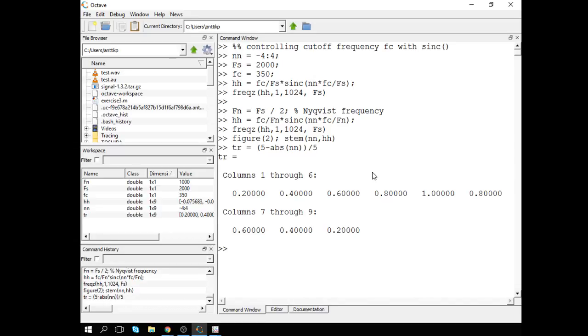Yeah, that's the triangular shape window. Now we can actually do the sinc again. Let's see, but we already have the sinc. Now we use the other window, not this box window, but we use the triangular window simply by selecting TR as the W function there and see what happens.